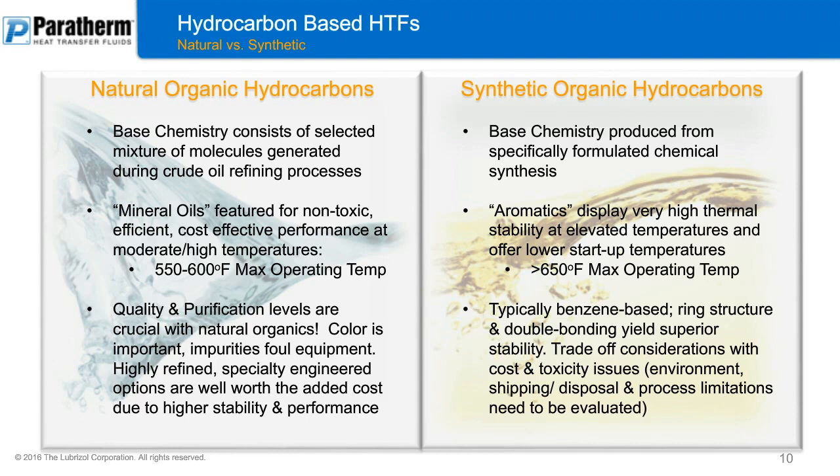So the trade-off considerations with that: in a perfect world, you would love to have something that's the most stable, that gives you the best range of temperatures. But the issue here is you have to trade that off with cost considerations. You also have to consider an environmental situation with the aromatic-based fluids. As you can tell, if they're benzene-derived, there is the consideration that you need to put in with the environmental issues, disposal issues, some process limitations that you have. All that needs to be taken into account when talking about the classifications.